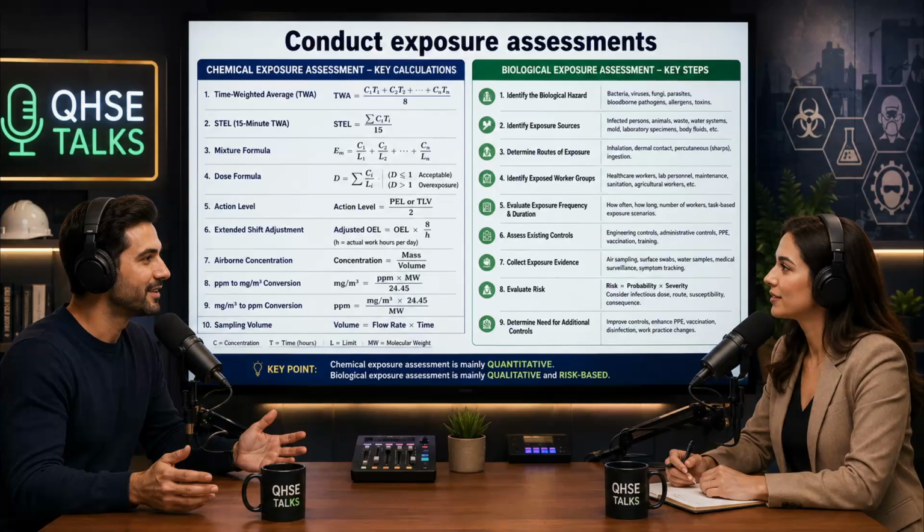Right. There is one limit that operates completely differently than the rest of these, though. The IDLH. Immediately dangerous to life or health. When I first heard that term, I assumed it meant a concentration where you literally just drop dead on the spot. It's a bit more nuanced than immediate fatality, though that is certainly possible. So what does it actually mean?